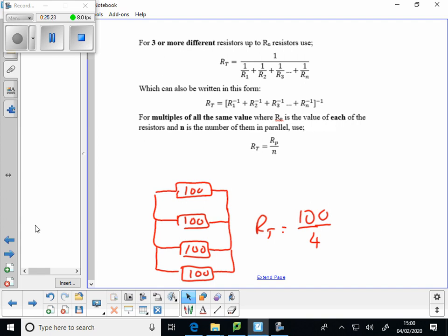And what's the other tip to remember about the total in a parallel resistor network? The little check that you got the right answer. Yes, the total is always lower than the lowest resistor in the parallel section. But that's the total of that parallel bit, not necessarily the whole thing. Again, there's a source of confusion there that might crop up a bit later.